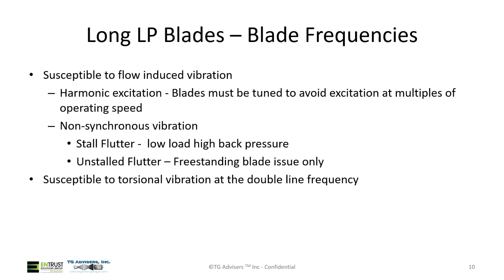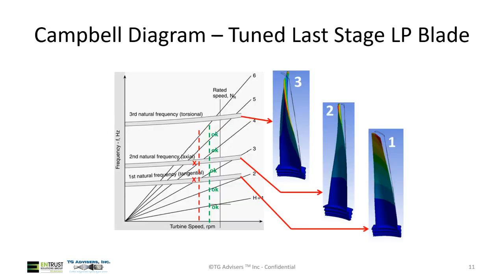So the other thing to know too is I mentioned during torsional vibration, some of the big blades can be susceptible to double line frequency. They can have frequencies in or around that range that can get excited by the torsional vibration if, when it's coupled to the rotor, it creates a frequency in that zone. So we have seen industry failures in the past, especially long ago, on blades of this size. So these are all things to vet during the process.